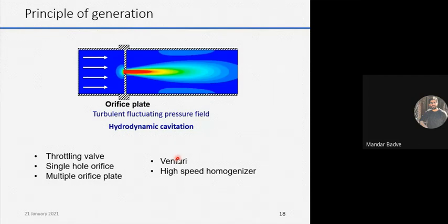So why does that happen? Because you're reducing the flow area. The rate at which water is coming from your tap is the same, but because you pinch your pipe, your flow area suddenly goes down and your water comes out at a high velocity. It creates a jet, right?